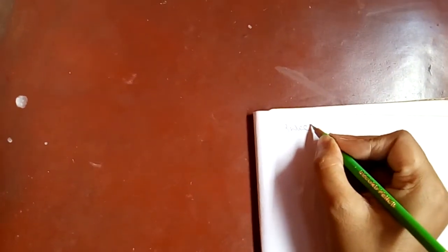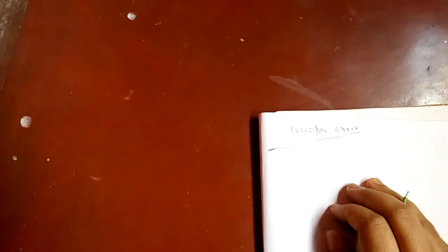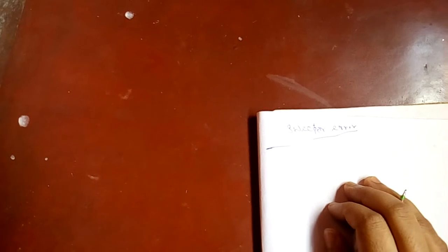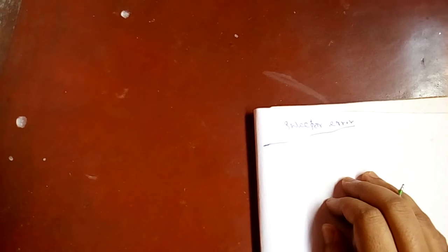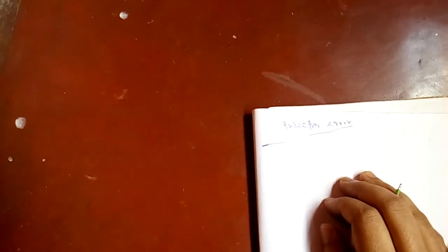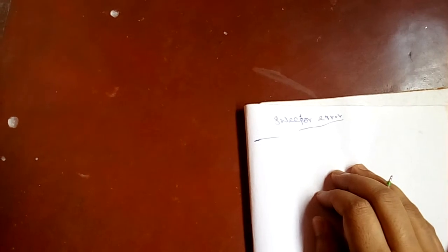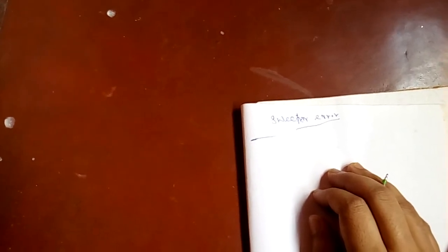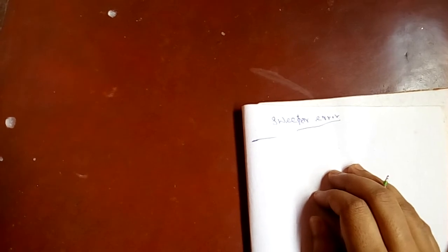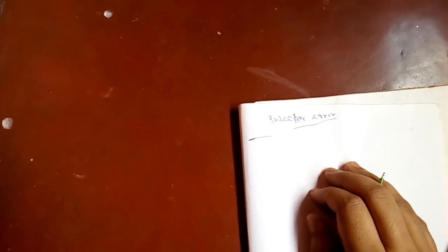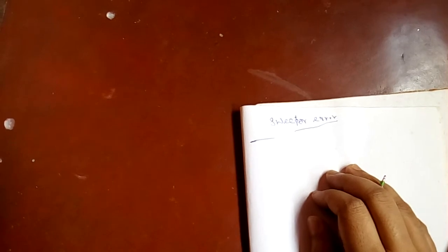So what is sweeper error? Sweeper error: due to the imperfection of the output of the generator, these errors are generated. Any harmonic produced in the frequency should be swept along with the fundamental but at a faster rate. For example, if we take the nth harmonic, it will be swept at n times the rate of the fundamental. So this harmonic may be within the pass band of the device being tested for part of the sweep, and out of the pass band for the rest.